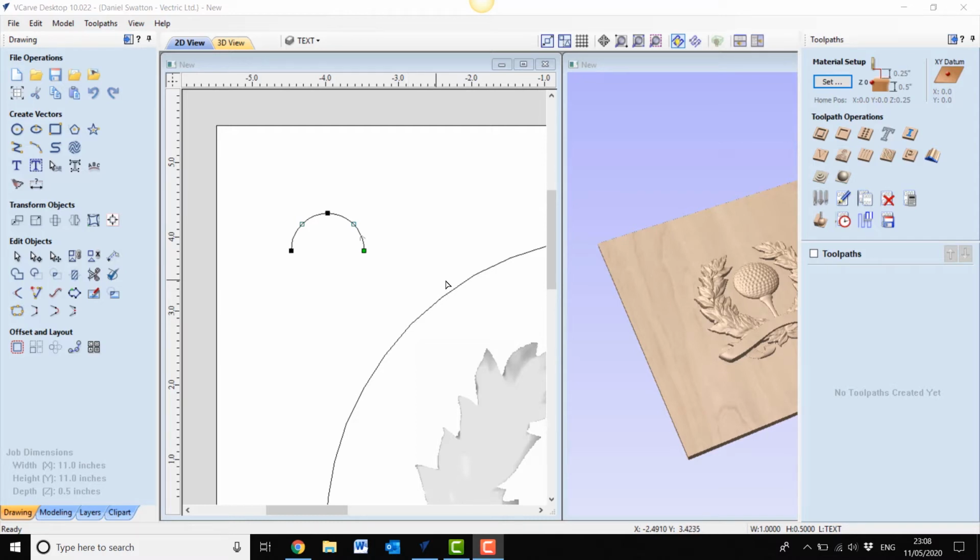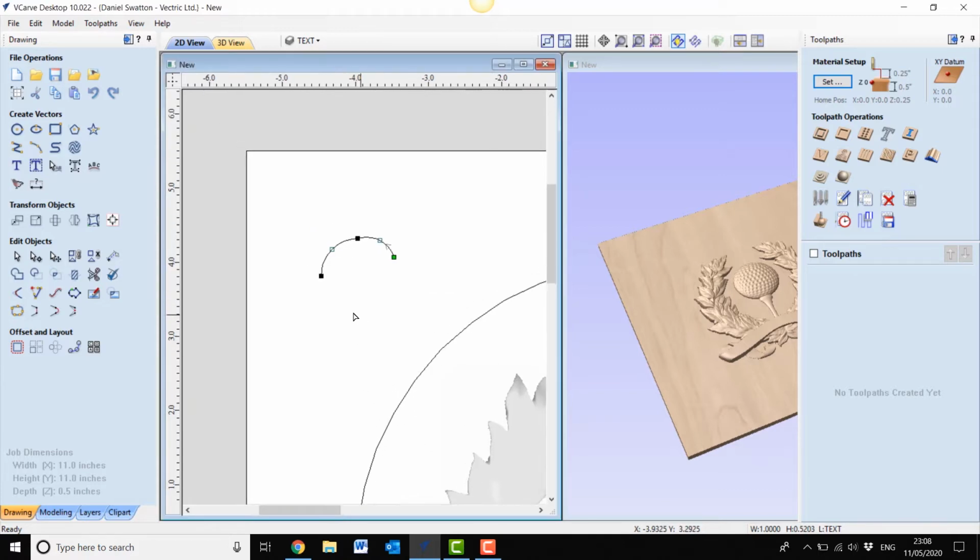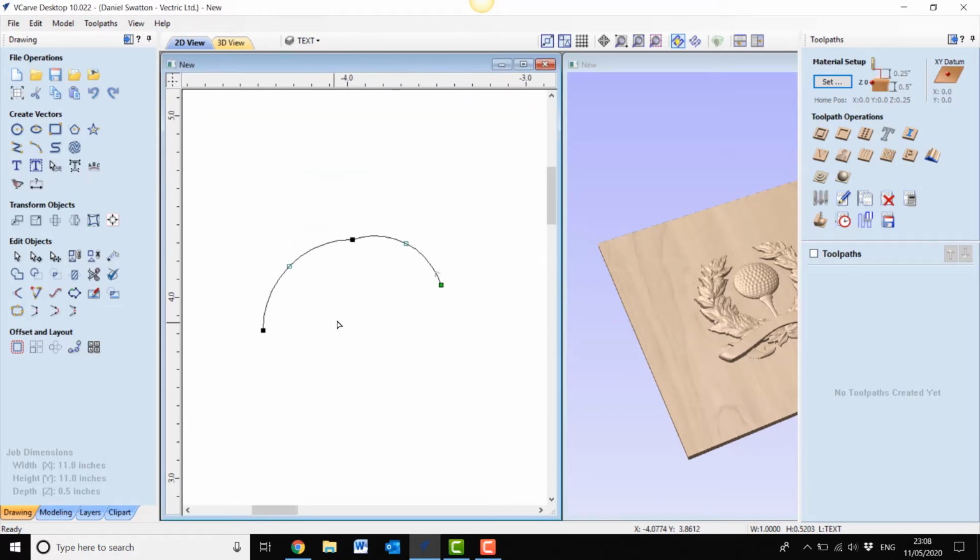But if we go on the inside where the laurel wreath is located, this is actually going to be just down to 0.25. So to do that, I do need to modify the actual cross-sectional shape. So I'm going to select the inside one now, and I've just selected it. I'm going to go to right mouse key properties and move this upward by 0.25 inches. So with that, I'm just going to apply that and raise it up, and we'll take a little bit of a closer look here.